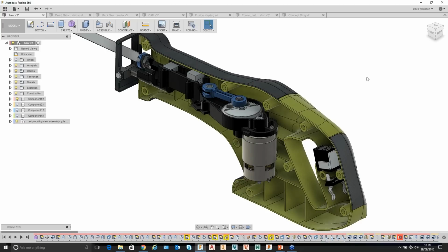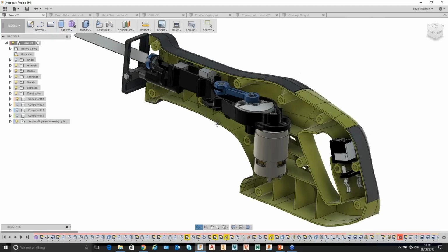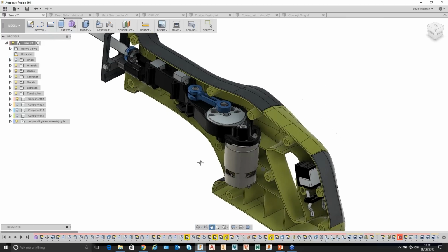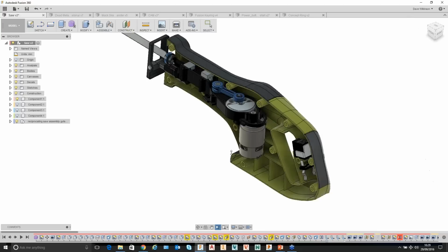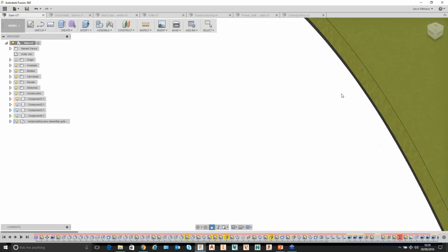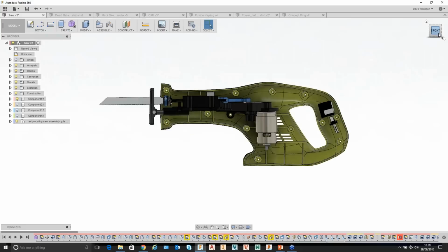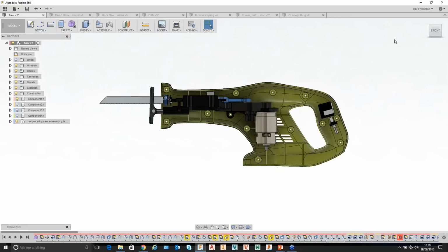So that's one thing. To navigate and move around the 3D environment, particularly for anybody that's not used 3D before, is very easy. We've got a range of standard tools here, so we can simply spin the model around very quickly and easily. We can pan and move around, zoom in and out, so it's very easy to get on with. But more than that, if we find ourselves lost or if something's disappeared off the screen, we have a view cube up at the top right here, and this view cube is standard across all of the Autodesk products in our portfolio, and it allows us to manipulate that view very quickly and easily so that we can work with the design effectively.